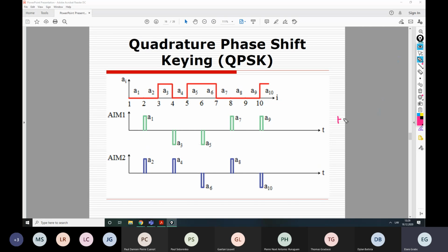And these two pulses are then used with their amplitude to generate accordingly plus sin for this duration. That would be sin signal. Sorry, cosine signal. First channel is cosine, not sin. So that would be cosine. Right? And the second channel generates sin with positive amplitude of the same frequency. Then we add them up together and obtain also harmonical signal.